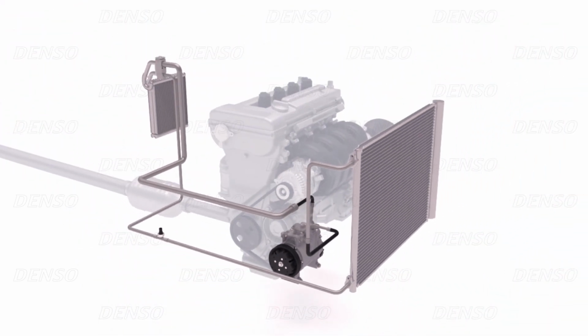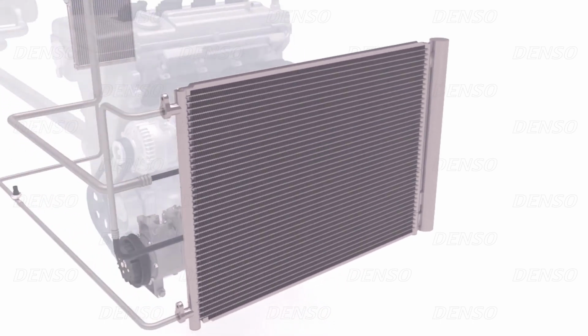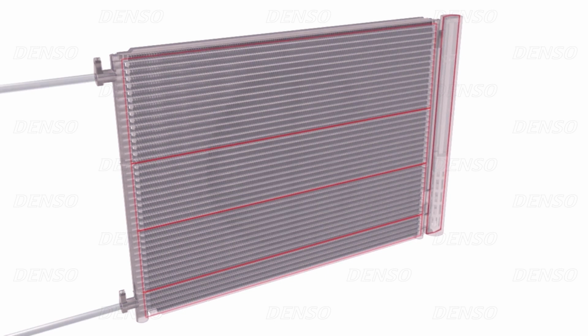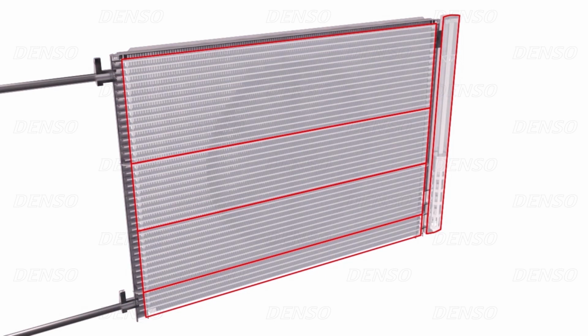The DENSO subcool type condenser operates using the same principles as a domestic radiator, because the condenser transfers heat to the air. The condenser is divided into four main sections: a gaseous section, to remove the heat from the hot gas, a condensing section, a gas-liquid separator, known as the modulator, and a subcooling section, with the high-pressure refrigerant flowing through these four sections in that order.